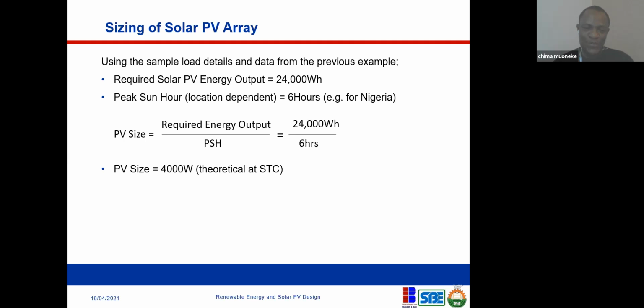So if that is the case, which is what you're asking, whereby you're using the energy directly from the PV and also being able to charge the battery, in that case, you have to modify the amount of watt hour that you need. So instead of 24 watt hour, you're going to consider the amount of load that the PV system is going to be powering, right? The PV system is going to be powering your load and then charging this battery up to 24 watt hour in a day. I don't know if that is clear, Jackson.